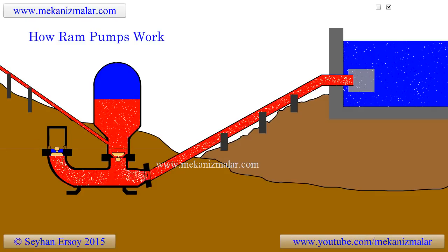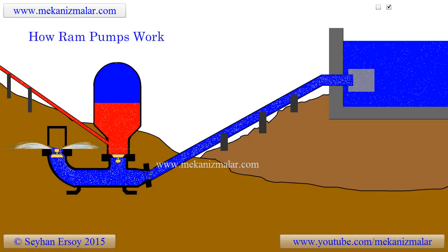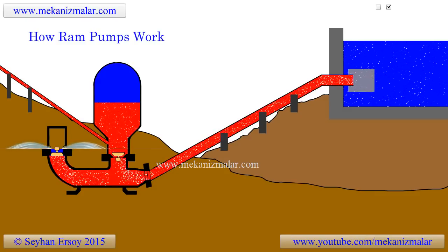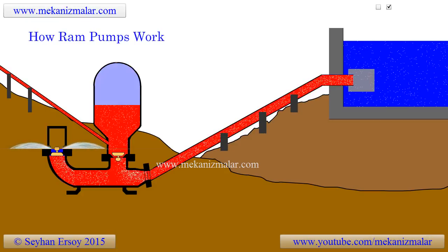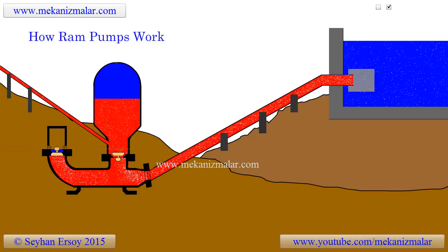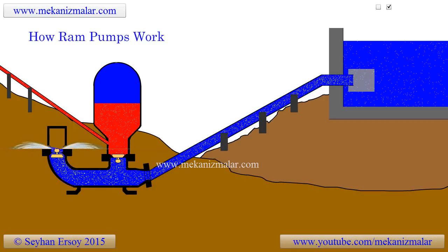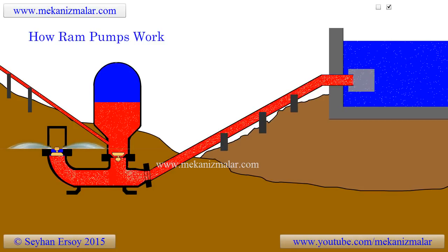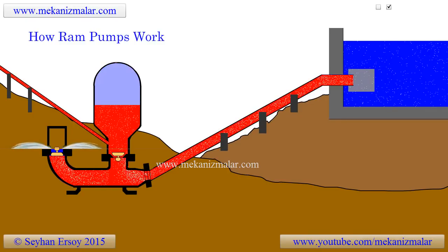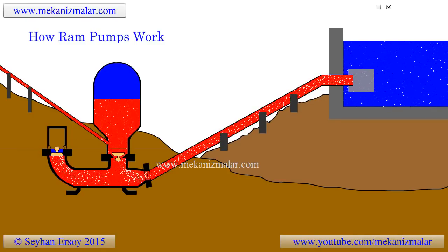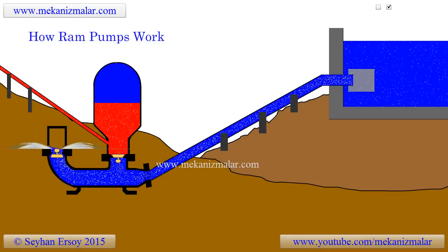The system may seem like it's disposing too much water, but it's not the inefficiency of the ram pump, but instead the requirement of the conservation of energy principle. If 10 liters of water per second is fed to the ram pump, and 2 liters of water per second would pump to 100 meters of elevation, this would violate the conservation of energy principles. But a quarter liter per second is a darn good flow rate for the system mentioned, and does not violate any energy principles.